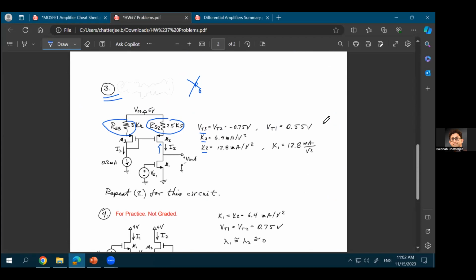The drain current, the RS2. Yeah, but you already know the current flowing through this path. That current multiplied with that resistance will give you the voltage drop at that resistor. So that's a simpler way to analyze it.